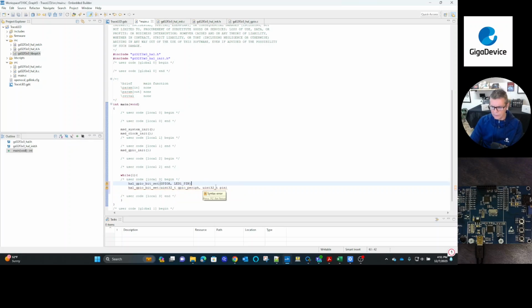Like I said, we're going to do a trace demo here, where we're going to light up LED 1, and then we'll need to turn off an LED, and then put a delay. So let's go ahead, we did a bit set, and we're going to do a bit reset.